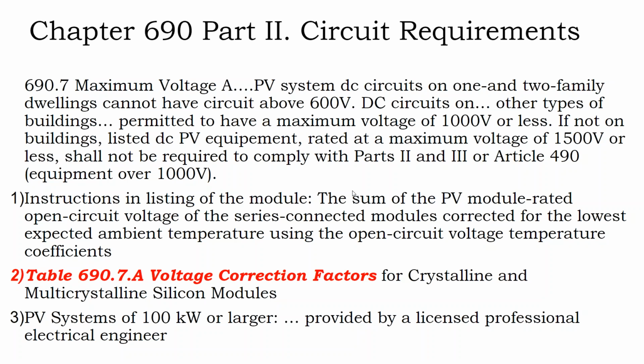Going from a 200 amp service panel to a 400 amp service panel, you're doubling the price of the service panel. When you go from a 300 volt cable to a 600 volt cable of equivalent gauge, you're just buying a little bit more plastic. You're not doubling the cable cost. So having that extra clearance of 1,000 volts can result in cost savings.